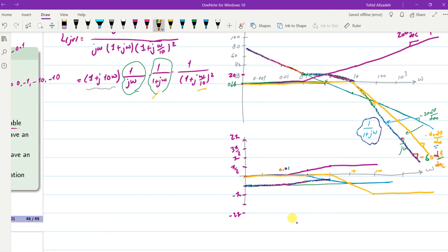And after that, we will have the final component affecting the phase of the system, which are the two poles at omega equal to 10. From this point onwards, you can see that the phase of the 0 that we have is cancelled by the pole at the origin. So only the three components will affect the phase of the system, and therefore the phase will start to decrease.